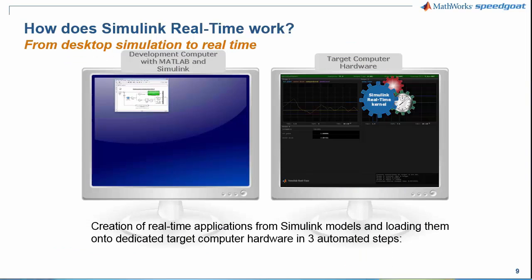Now that we know which part of the software can be found, I want to take 2 minutes to refresh the workflow knowledge, from simulation to real-time hardware. To deploy a Simulink model as a real-time application, it only takes one push of a button, which automates 3 different steps. We start with a Simulink model on our development computer, where MATLAB Simulink is installed.